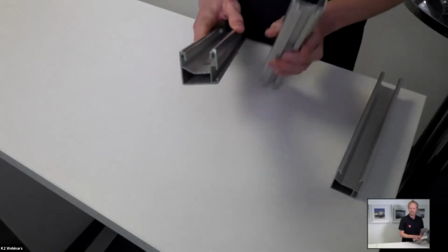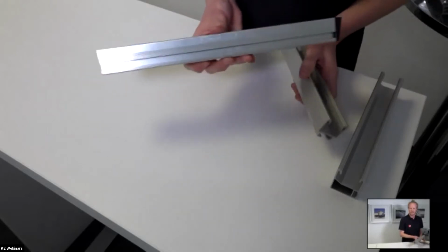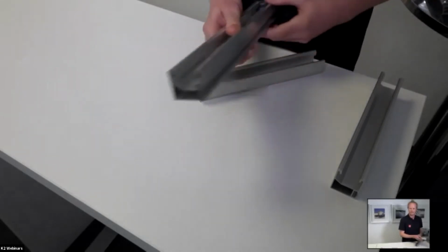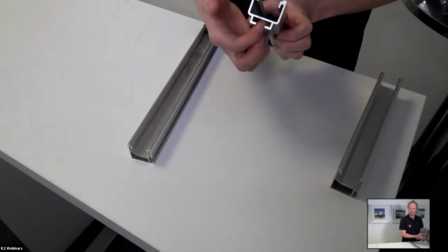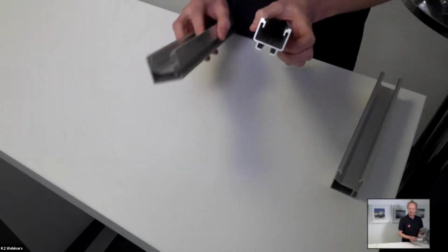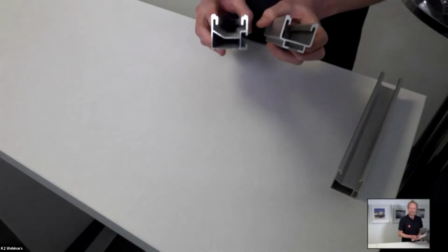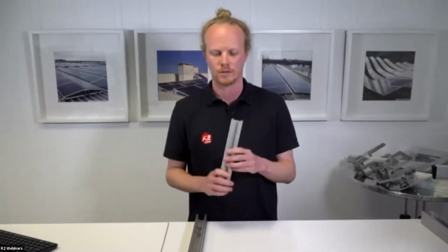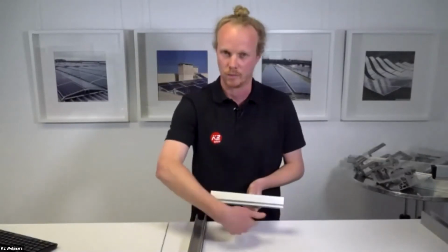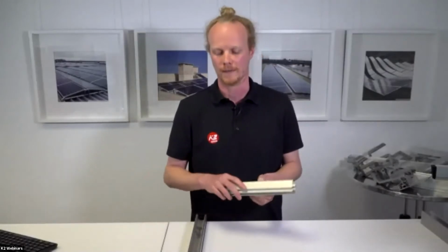So the difference though is the positioning of the fasteners. For the SingleRail, we have that on the side, and the SolidRail, we have that on the bottom. And the difference has two sort of meanings for your project. The SolidRail with it on the bottom is slightly easier to extrude. The geometry is a little simpler, so it's a little bit cheaper product. The disadvantage, however, is that the fixation is from underneath. I'll show this a bit later, but when we're fixing it, we have to work under, and the installation time takes a little bit longer.